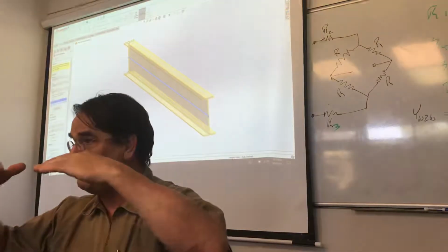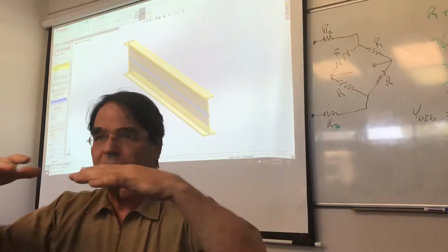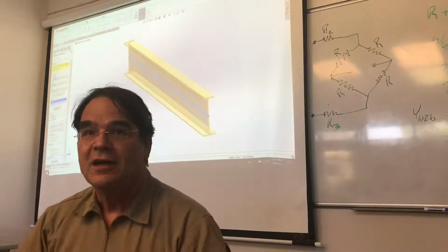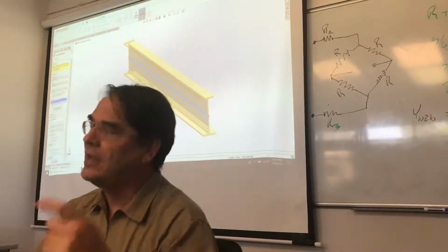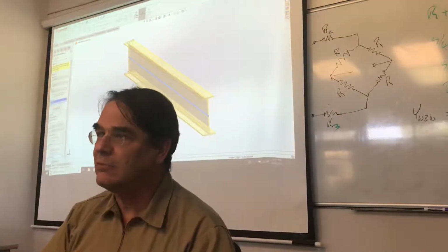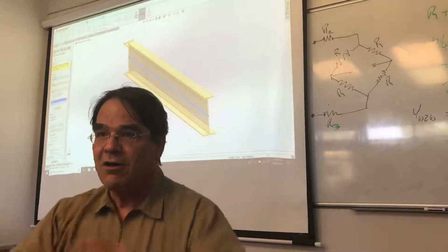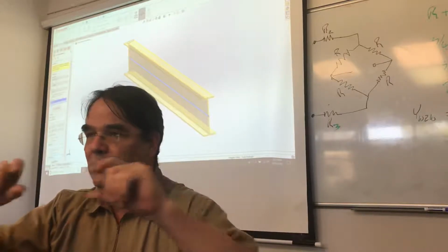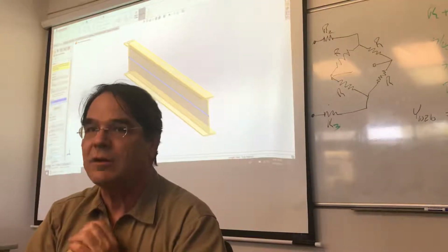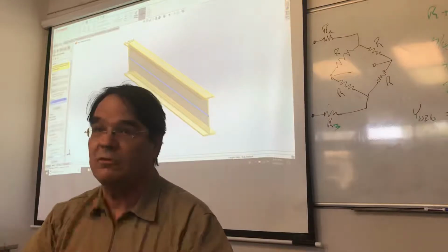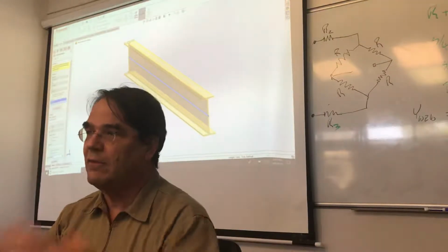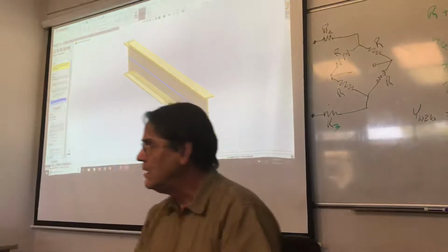They have an angle, not a very big angle, like 15 degrees, but there's an angle on the S sections. The W sections and the HP sections and some of the other newer sections all have flat flanges, constant thickness all the way across. They're the ones that we all use these days. They're much cheaper than the S sections for a variety of reasons.